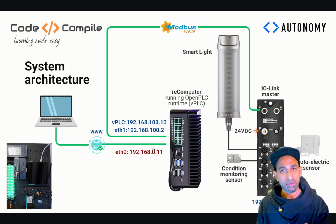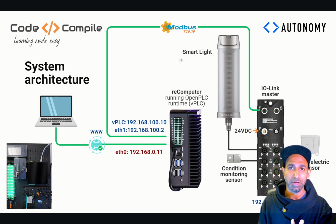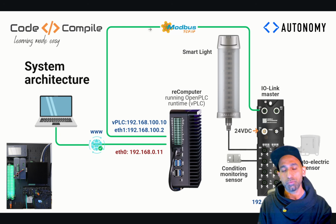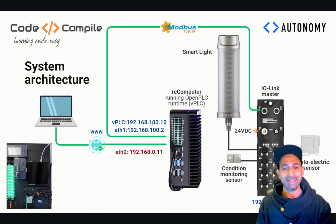And the other port, which is isolated, is connected directly to my IO-Link master. All right, so this port is like an industrial Ethernet port. And this is communicating via MODBUS TCP/IP. I will show you shortly how you can do that. And I have not shown you here, but I'm also connected to this network with my laptop so that I can show you how you can access the web server. So it's not mentioned here, but my computer, with another extra port, is also connected to this network. So these are the IP addresses. This is the IP address of my edge device for my Ethernet 0. This is for Ethernet 1. And you can see that the virtual PLC has its own IP address, and this is running in the edge device.